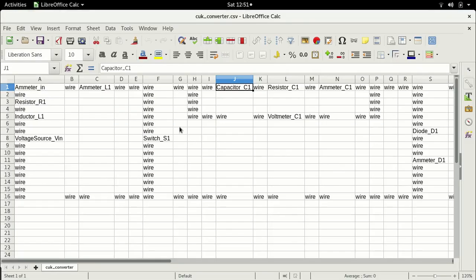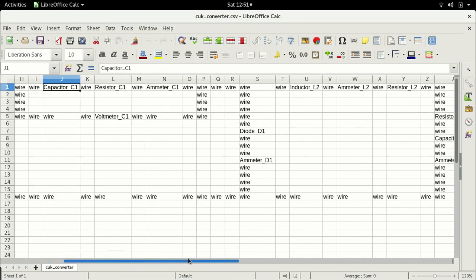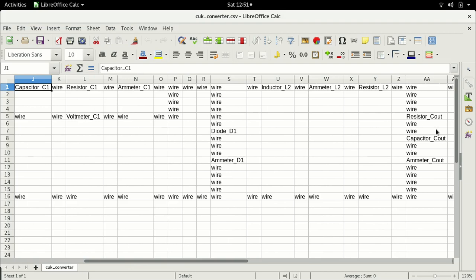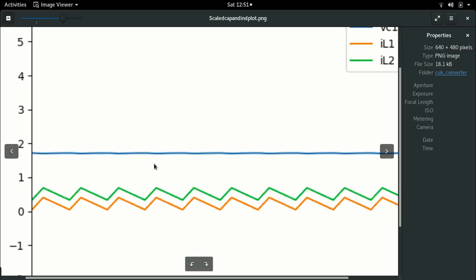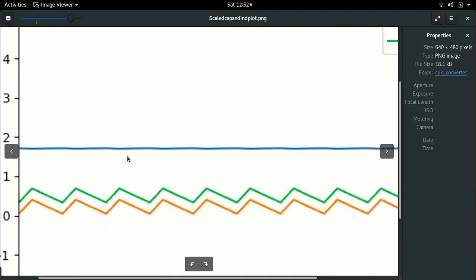Now, at the same time when the switch is turned on, the capacitor is discharging through the switch. And this discharging capacitor is charging the output voltage and is charging the inductor. So the inductor current is rising. But the inductor current is rising because the capacitor is transferring energy to the inductor, right? That's what you see in this line. Of course, it's a little difficult. It would probably at this point of time be wiser to go and plot it using Matplotlib. Maybe I will show you how to do that in another lecture. But this shows you that.